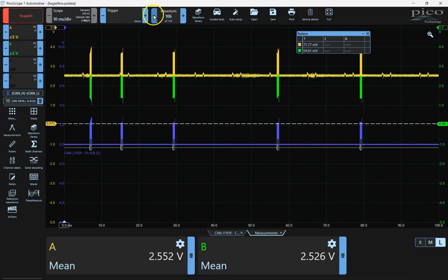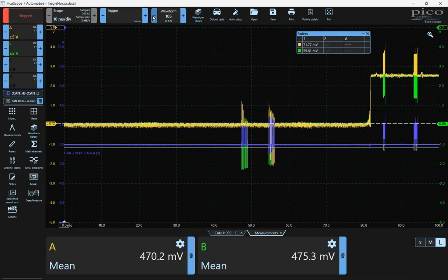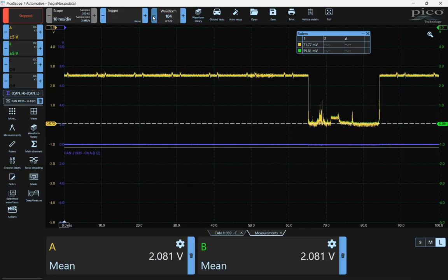2.5 volts. So if you were watching this with the meter like the tech did, one thing, it's hard to watch your meter while you wiggle the wire harness around. But if we had a peak hold, like a Fluke 88 or a Fluke 87, I might have been able to find this without the oscilloscope. Even with the oscilloscope, it was very obvious what our problem was.